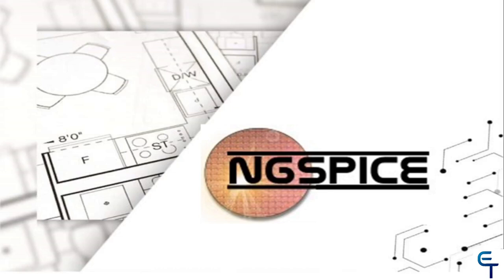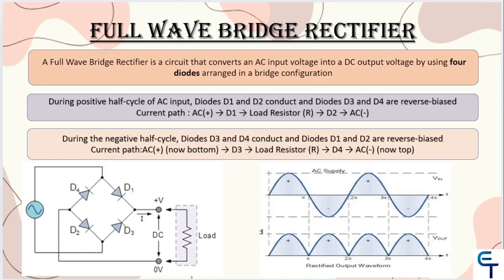In the previous video, we saw how to simulate a half-wave rectifier. In this video, we are going to simulate a full-wave bridge rectifier using Ngspice. A full-wave bridge rectifier is a circuit that converts AC input voltage into a DC output voltage by using 4 diodes arranged in the bridge configuration, as you can see here in the circuit diagram.